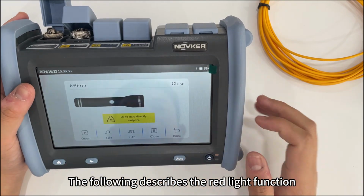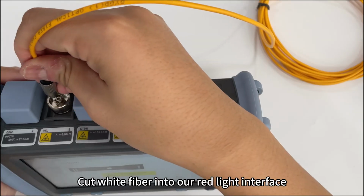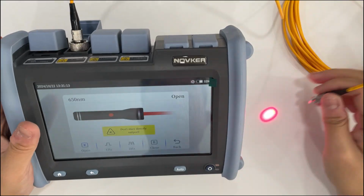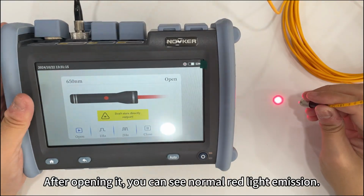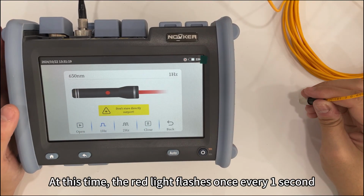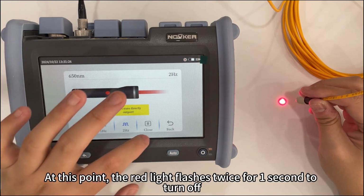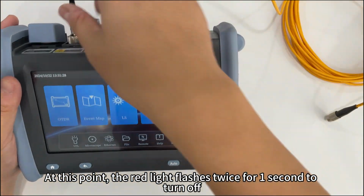The following describes the red light function. Plug the fiber into our red light interface. After opening it, you can see normal red light emission. Switching frequency. At this time, the red light flashes once every 1 second. Switch to 2 Hz. At this point, the red light flashes twice per second.